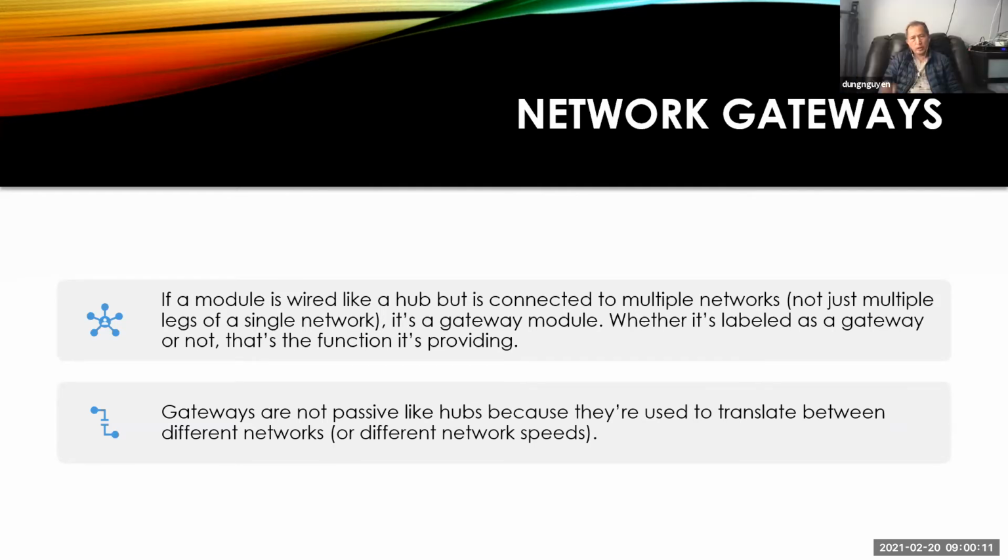But what if the gateway module goes bad and the whole system shuts down, because now I can't talk to those modules on the other side of the network? And if the gateway module is the module I have to go through to talk to the car, I'm not talking to anybody. After our break, I've got some examples where I have to go through a gateway module to talk to anybody.